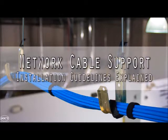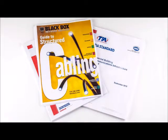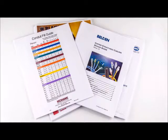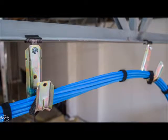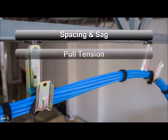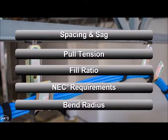Network cable support installation guidelines explained. There are many guidelines and rules for spacing and installation of non-continuous cable supports. These are given in the NEC and TIA standards as well as cable manufacturers' instructions. Local building codes must also be taken into account. There are 5 major guidelines to follow when using a non-continuous cable support such as a J-hook: spacing and sag, pull tension, fill ratio, NEC requirements, and bend radius.